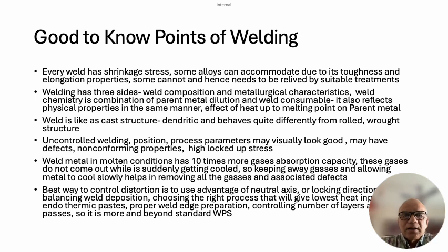Now, unless we give sufficient time for the weld to solidify, and ensure during solidification that these soluble gases absorbed into the molten weld metal are released, they will reflect as porosity or some kind of inclusions.